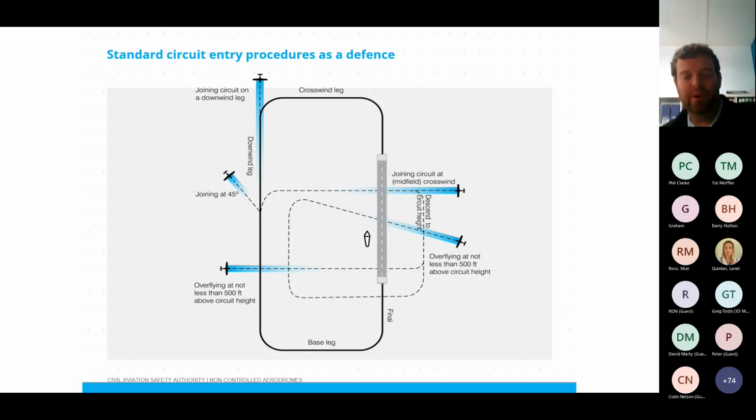So that's really the main reason we might teach them to do straight-in approaches at commercial level. But just like Chris said, to be safer and to give yourself more time, we always teach at PPL or RPL level to do overhead approaches, basically to assess the field. By doing straight in, you give yourself far less time to plan your approach. You might have a particular picture in your head of how you're going to approach the field on final, and hopefully, without anything going wrong, land the aircraft.